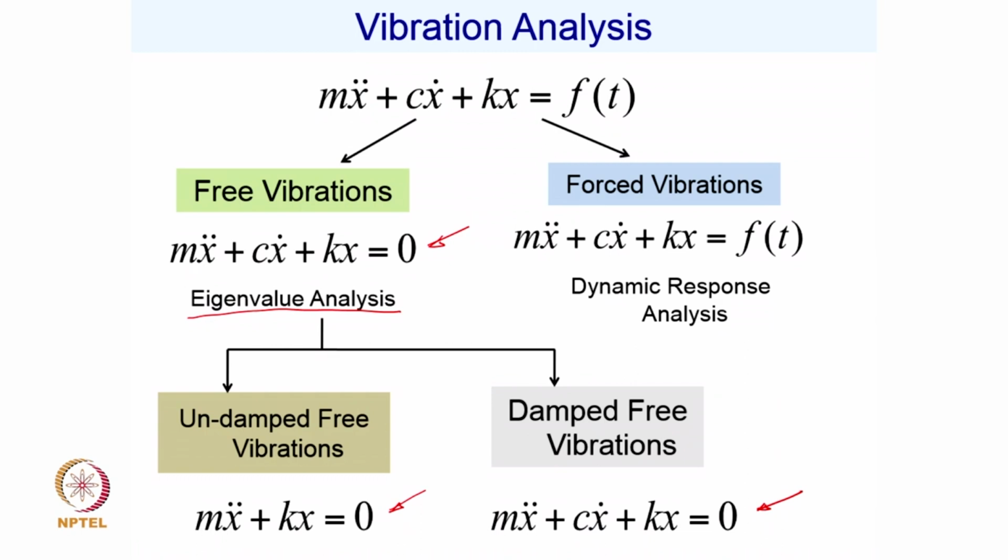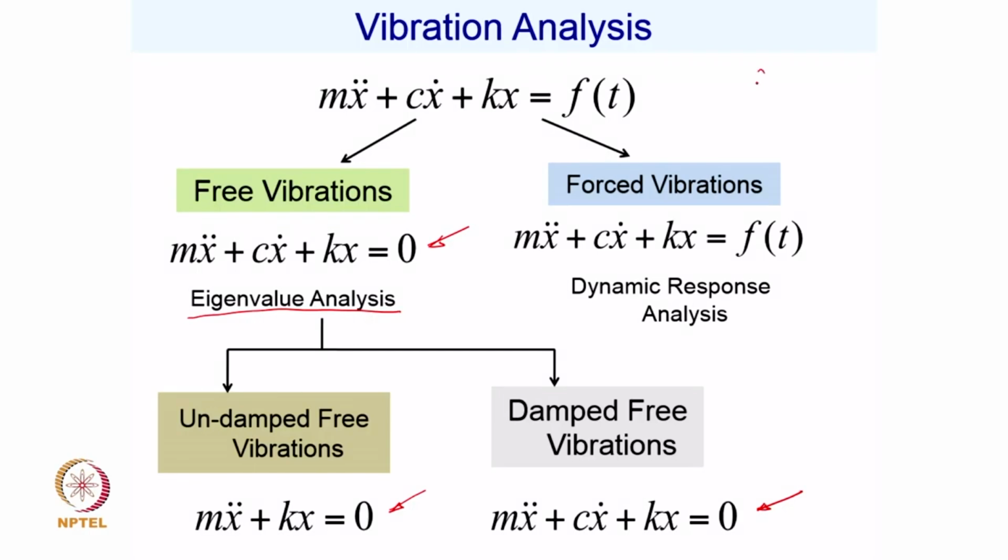And obviously, you know that for us to ensure that the system works away from any possible resonance, we should in fact know the natural frequencies of the system. So, when we define the excitation function for our mechanical system, for example, the engine operating speed, we define what is this excitation function, maybe F cap cos omega t, and then in that case this omega is your excitation frequency. Now, once the rotational speed is fixed, to avoid resonance, obviously you would like to know what your omega n is, the natural frequency.